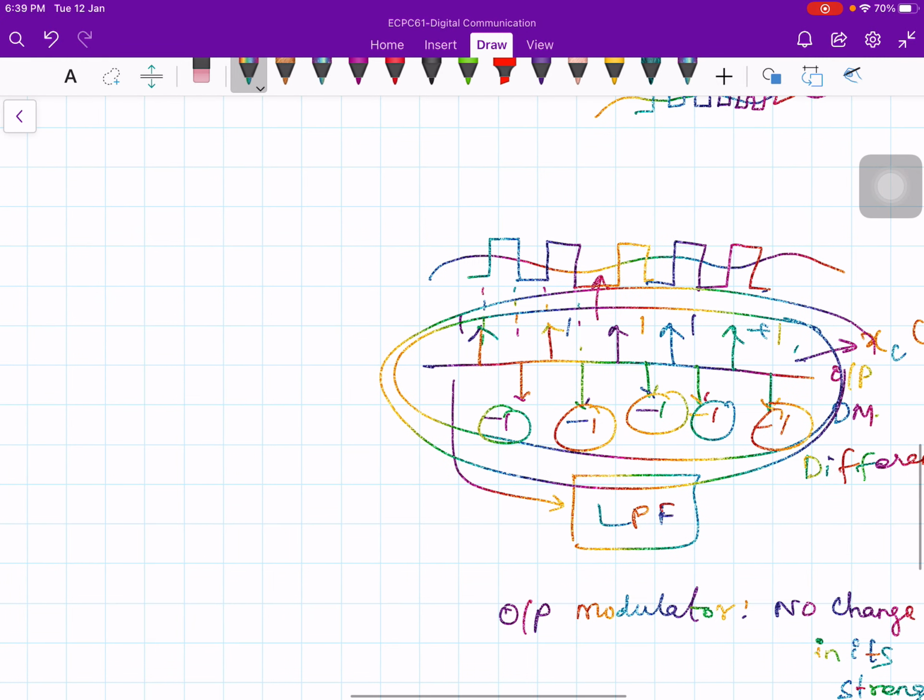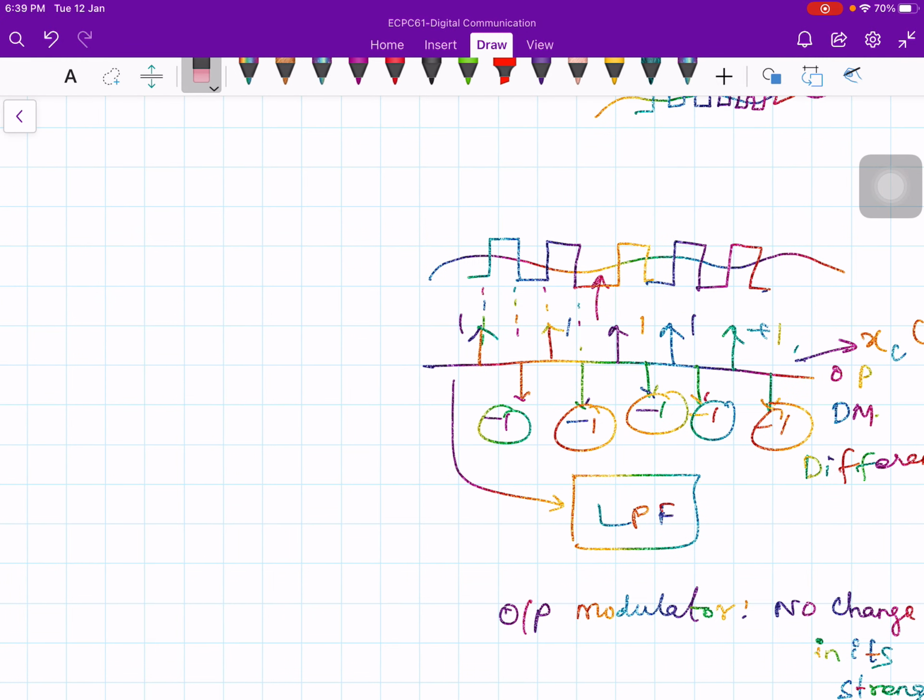So alternatively, it is positive and negative. In this situation, what you do is give it to the low pass filter, right? The delta modulator produces an alternate sequence of positive and negative impulses, and this system will interpret it to mean that the step size as it exists is too large. When will you get these positive and negative impulses? When the step size is too large. Therefore, it must be made small. How will you do that? Just pass it through the low pass filter.